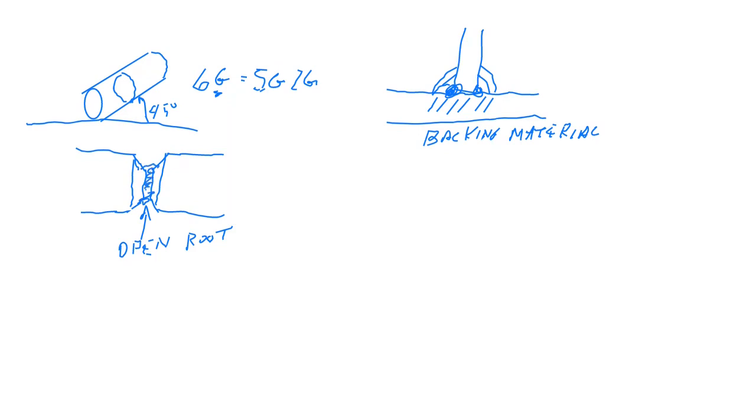and then I can fill it and cap it and make a good high quality weld, if I can do all that to an open root, that automatically qualifies me for any weld that requires a backing ring or a backing plate or any fillet weld in any position.